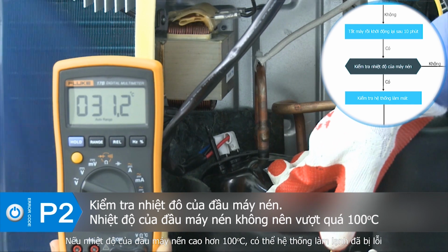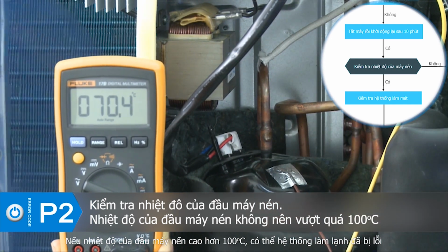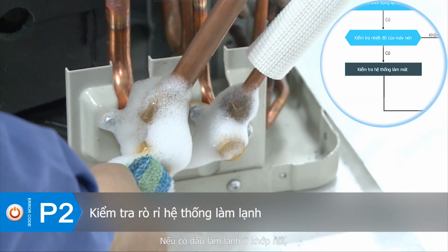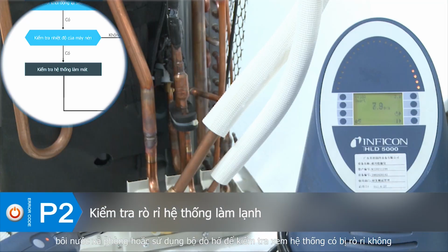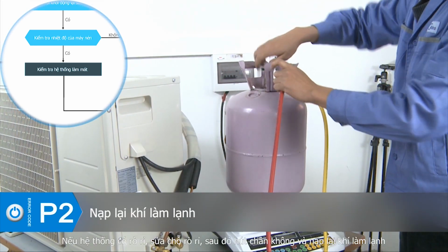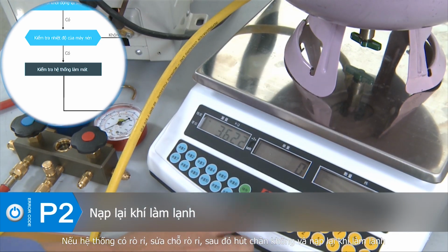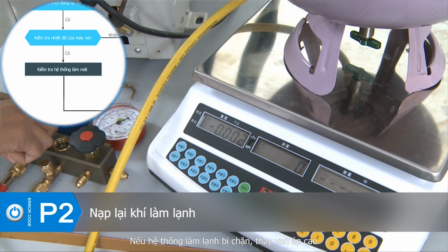If the temperature of the compressor's top is higher than 100 degrees Celsius, it could be the refrigeration error. If there is refrigerant oil on the joint, apply soapy water or leak detector to check if there is any leakage of the system. If there is any leakage in the system, repair the leakage, then vacuum and recharge the refrigerant. If the refrigeration system is blocked, replace the high-pressure valve.